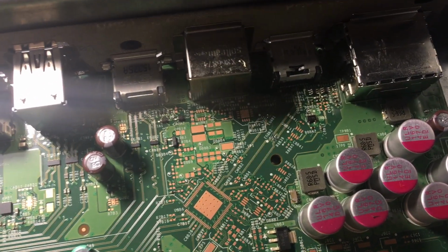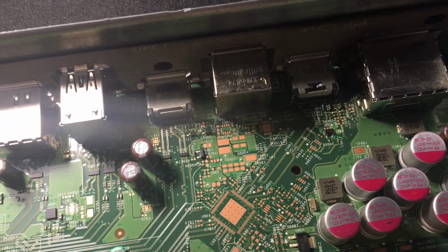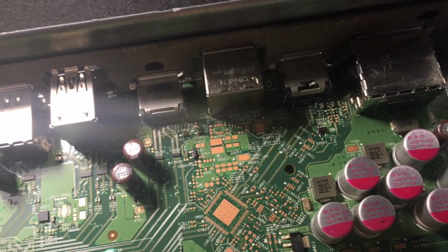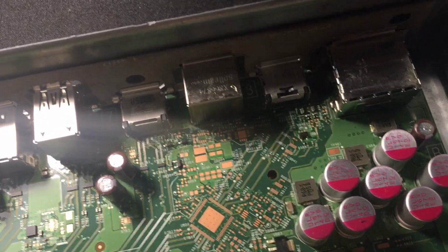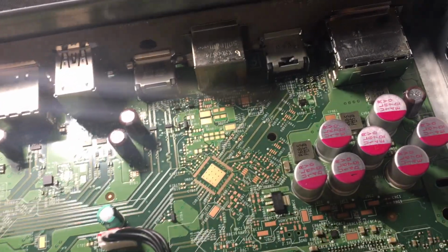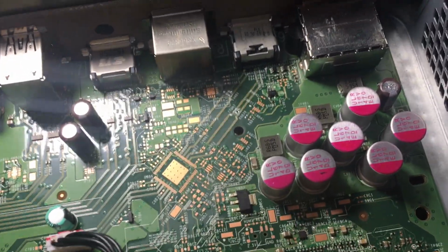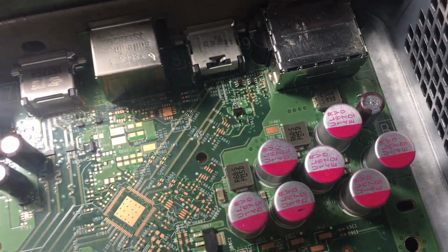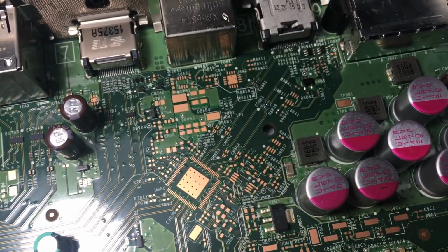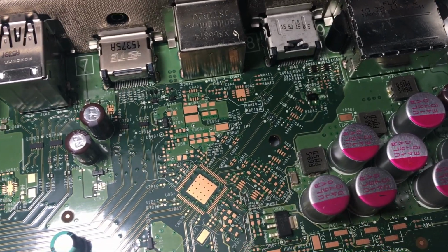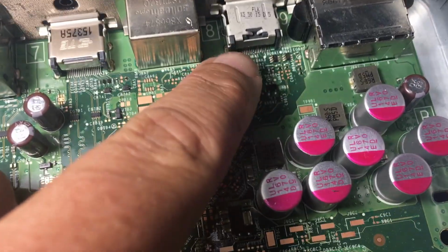it's also hard to show you because I don't have a great camera for it. But I'll link you to Andrew Paul's video on how to test the filter. I don't think most people are going to be concerned with that. This isn't something that everyone's going to want to do, and you'll see when I change the actual HDMI port that it requires quite a bit of cutting and soldering, and I used low melt solder to get those back pins off in the back there, if you can see that. And yeah, you can see the 19 pins that I'm referring to there on the back.